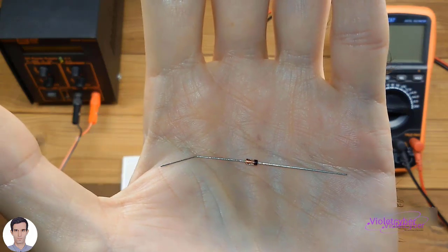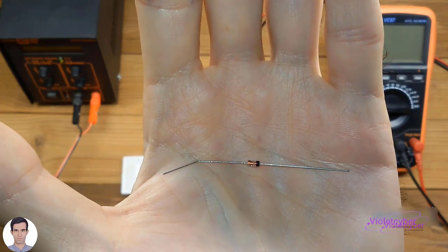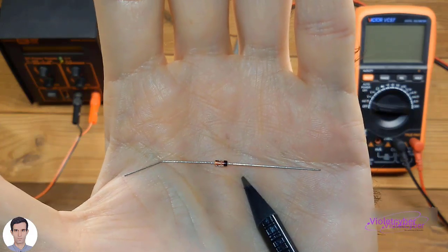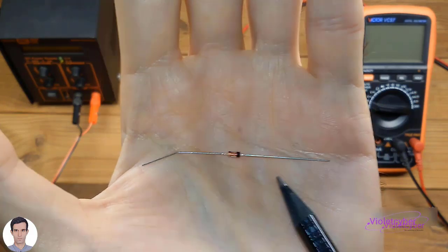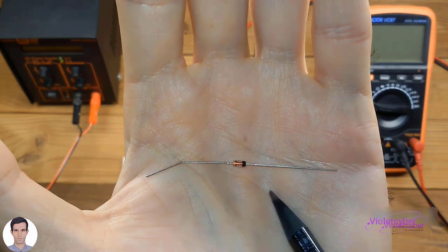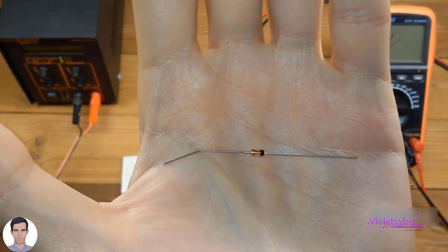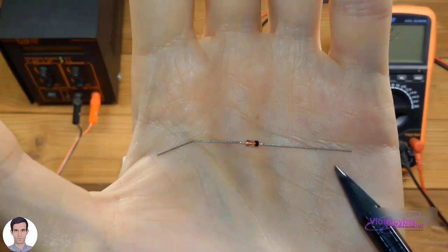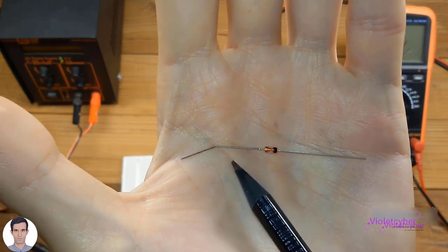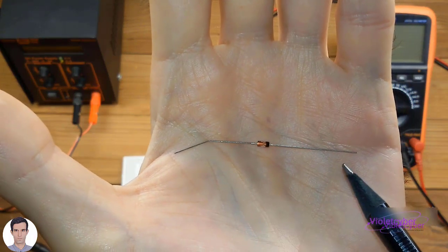However, for the Zener diode to conduct current and voltage in the reverse direction, there is a condition. The reverse voltage must reach the breakdown voltage threshold defined for the diode so that the Zener diode can start conducting and allow current to flow in the reverse direction. If this Zener diode is a 5-volt diode, for example, and we apply a reverse voltage of 3.3 volts to the cathode, the diode will not allow the voltage to pass in the reverse direction. However, if we increase the reverse voltage to 5 volts, the diode will allow the voltage to pass and will conduct current in the reverse direction.